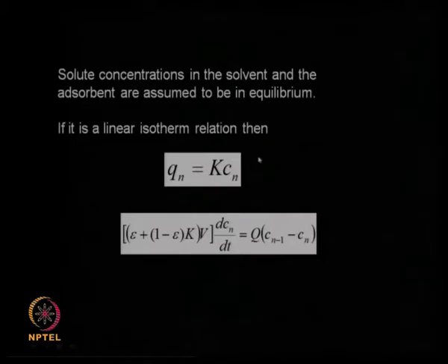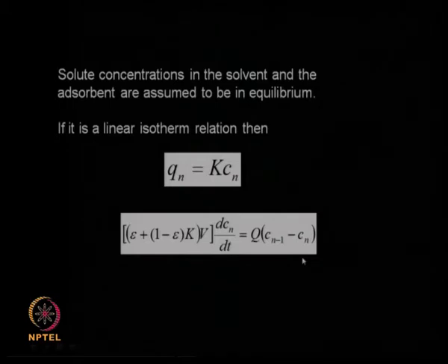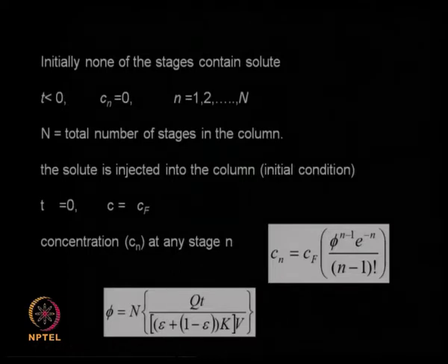Please note that we had considered a linear isotherm, that is why we are able to combine all these into a single term. If you consider non-linear equations, we cannot solve them analytically, but once you consider a linear isotherm relation, we get a series of differential difference equations, and then it is very simple to solve analytically. So, let us not go too much into the analytical solution procedure, but you need some initial conditions as well. If you want to solve any differential equation, we need initial conditions.